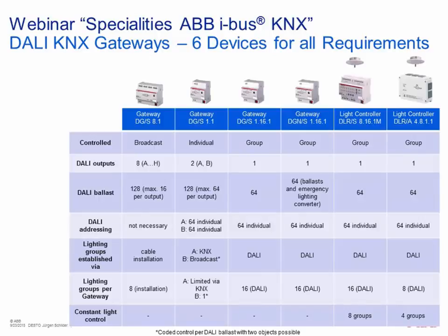Yeah, and DALI, something you should know, of course, as well. ABB has been offering DALI gateways for many years already. And up to now we have 6 different devices. So a big family covering all requirements on the market. Starting from a simple 8-volt DALI gateway to connect DALI ballast and operation only via broadcast, means no individual access to the lamp. Then the next one here, which gives you individual access to each of the 64 lamps connected. If you want, you can operate them completely individually, but also via groups. And you program this in the ETS via group addresses.